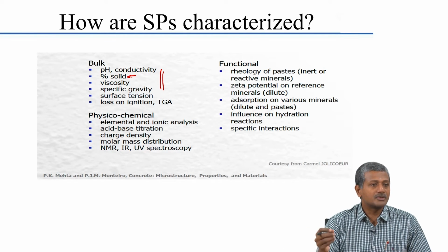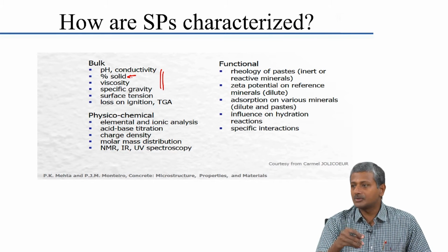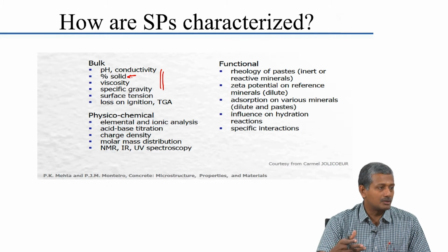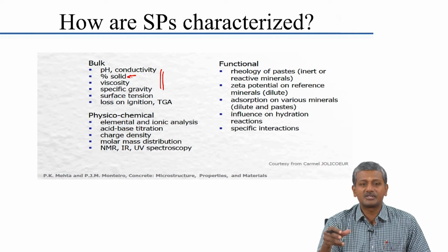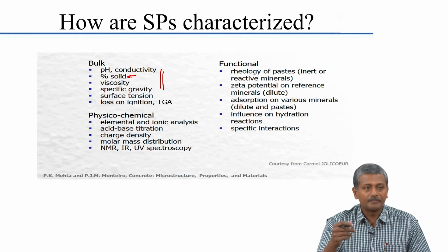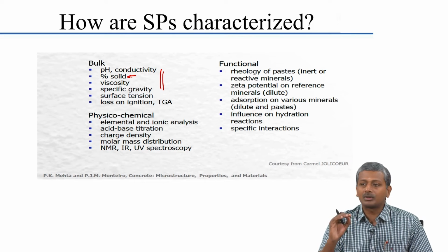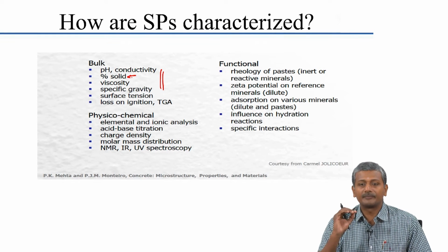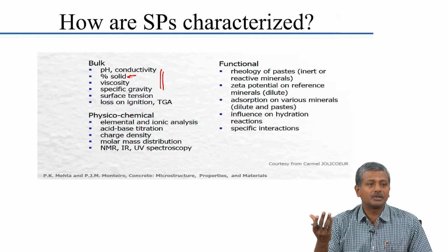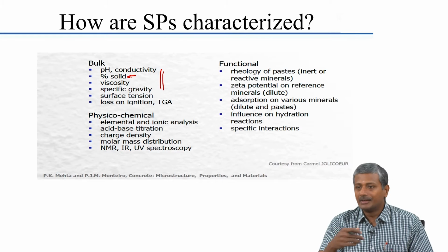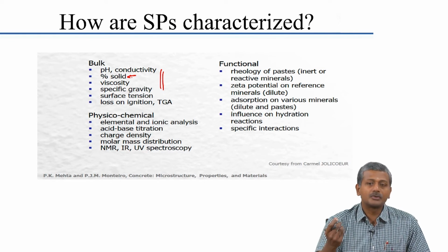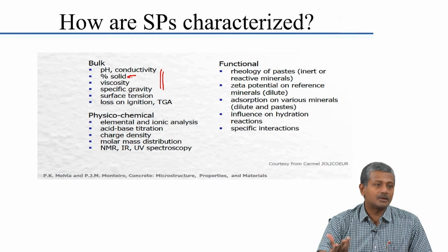water. These solids are dispersed in water because they are water soluble, and that is an easy way of dispersing them within the concrete. If you put the solid material into concrete, dispersing becomes difficult. That is why most superplasticizers are sold as liquid formulations. So, it is very important to understand what the solids content of the liquid is. How do you determine solids content? Just take it to a temperature of more than 105 degrees Celsius. In most cases that will drive off all the free water and you will get the solid ingredient remaining. Mostly that is what is done, and it can be easily done in a QC lab